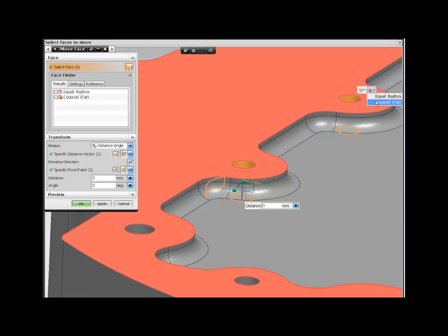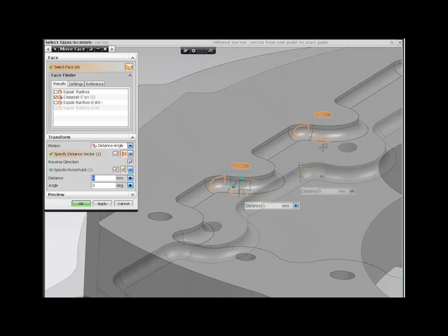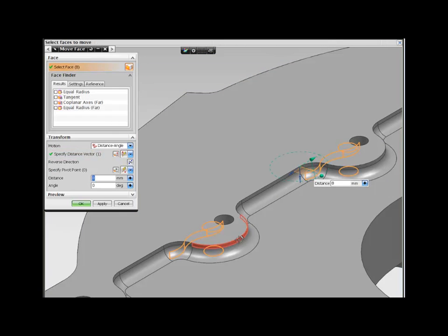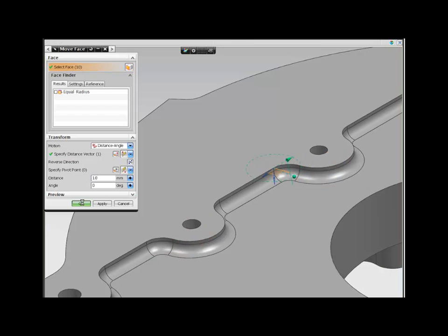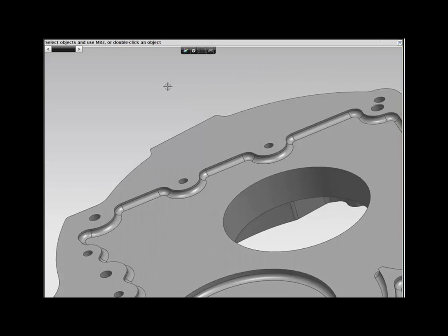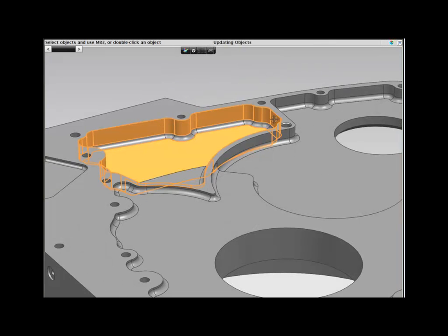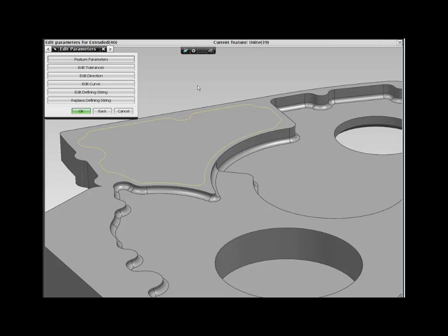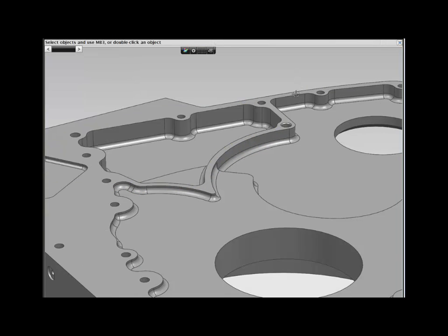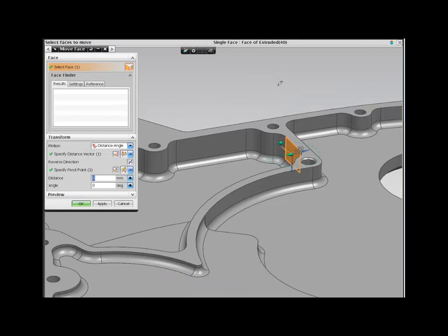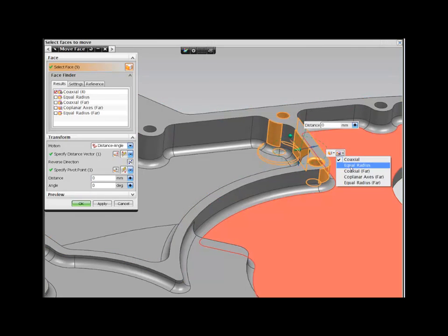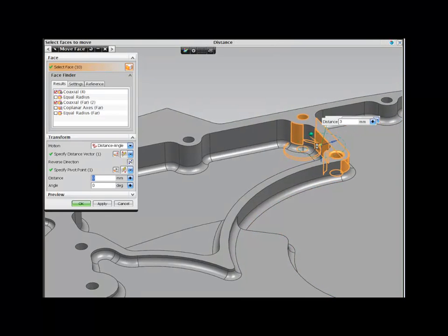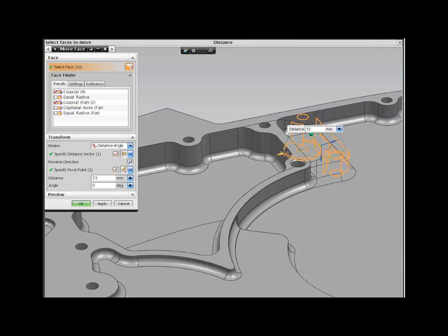Design Freedom lets you select intelligently, like coaxial relationships with active selection, a key component of synchronous technology, while still being able to add individual geometry during the edit. Now you want to move the rib that separates these 2 pockets. The original engineer made this part using 2 separate sets of geometry, so moving the rib by feature editing could be time-consuming. Design Freedom makes this simple. All you need to do is select the geometry you need to change and drag it to its new position.